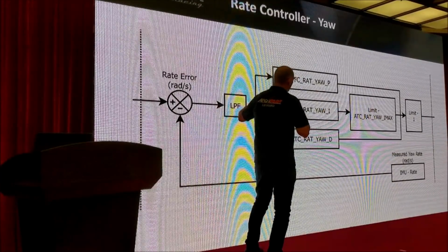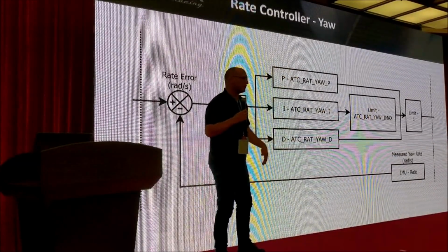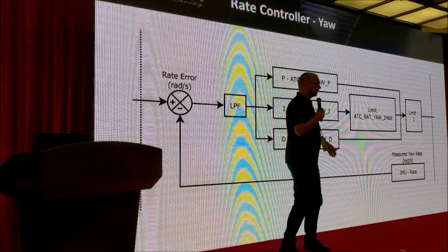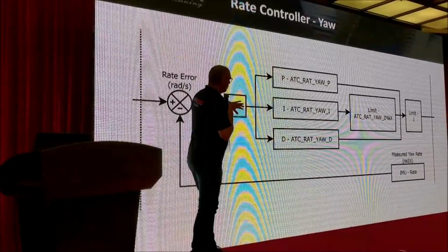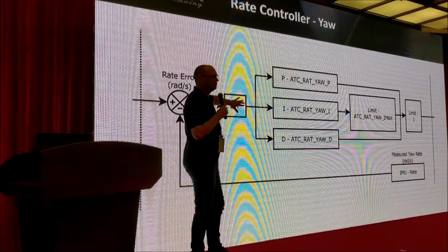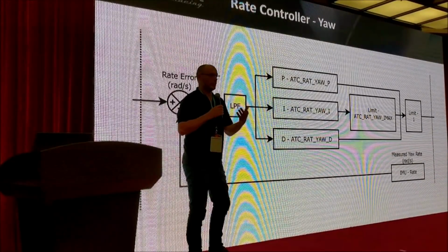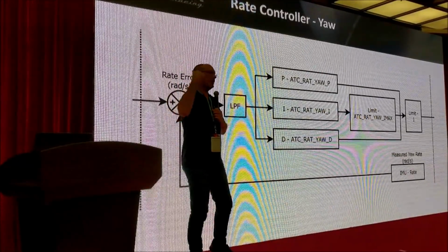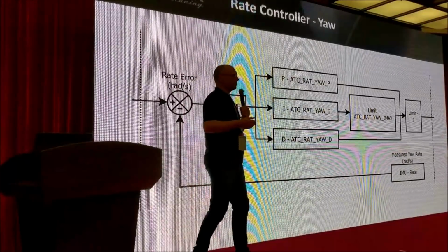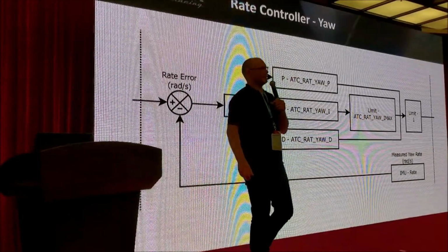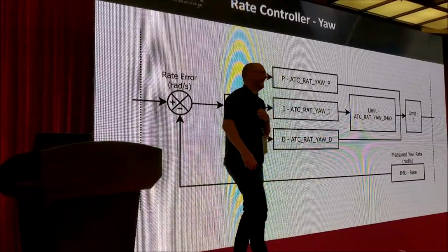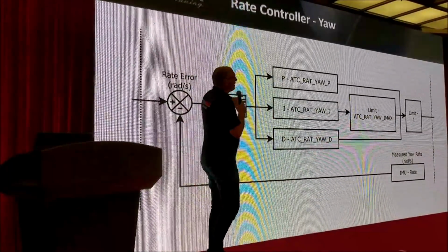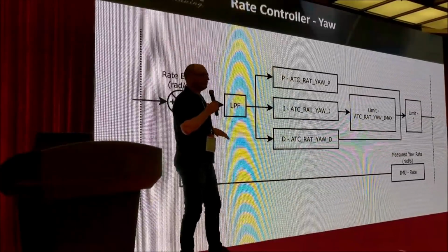And so in ArduPilot, for most aircraft, in ArduCopter, we actually leave the D term 0. And we actually control that mechanical D term from the interaction of that system and the fact that we've got this inertia of the propellers and motors providing a mechanical D term, and I really apologise to the translators for this bit. So that's why this filter is out the front.